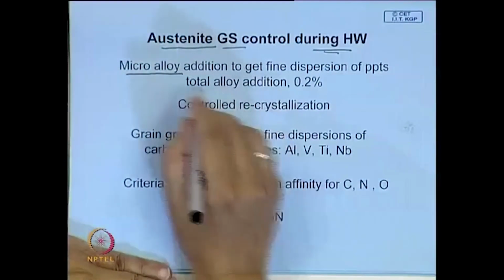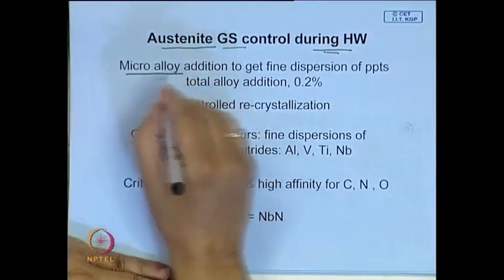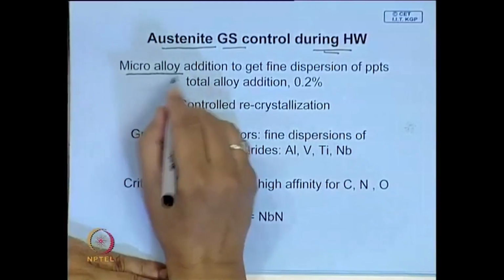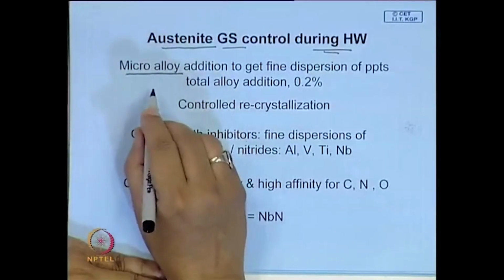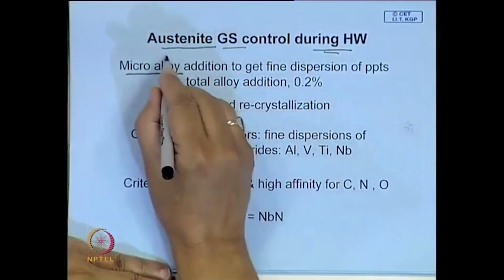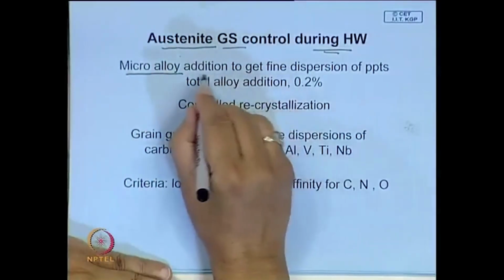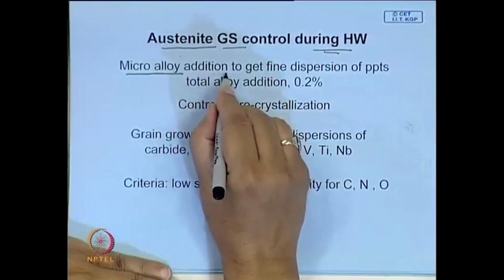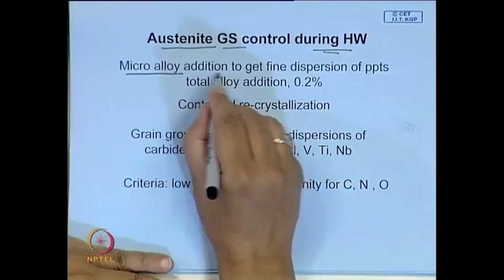Say normally iron carbide dissolves at quite a low temperature. So, this iron carbide or cementite is not very effective in suppressing the growth of austenitic grain. And we try to add certain very strong carbide or nitride formers, which are much more efficient in blocking or pinning grain boundaries.